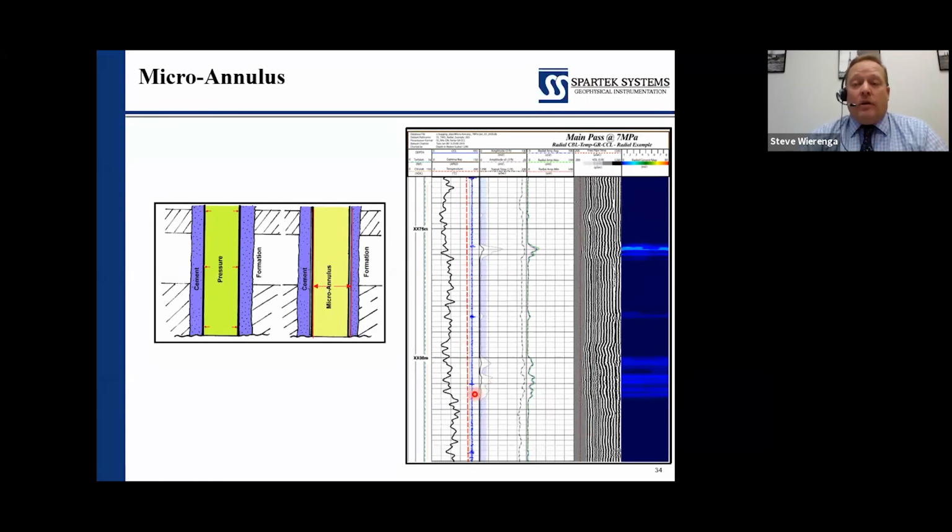Depending on what the well is doing and what we're producing, if we're in a fluid, so if this was an oil to fluid interface, pretty rest assured that we're probably okay. That microannular space is small enough that we're not going to get that fluid transfer in that microannulus. It is a very, very tiny gap. If we have a gas, that's a different situation, and we're probably going to see some communication there with gas.